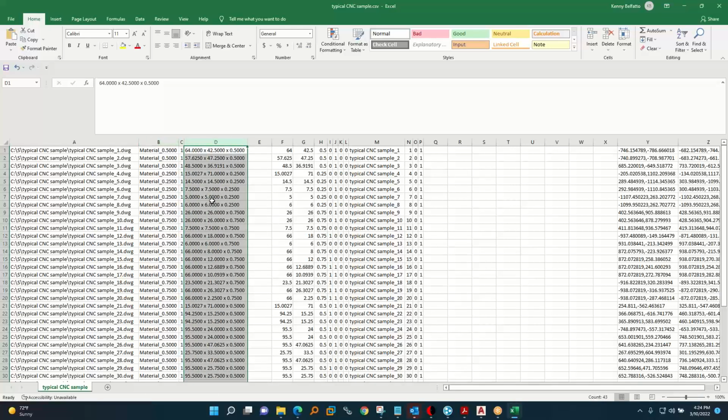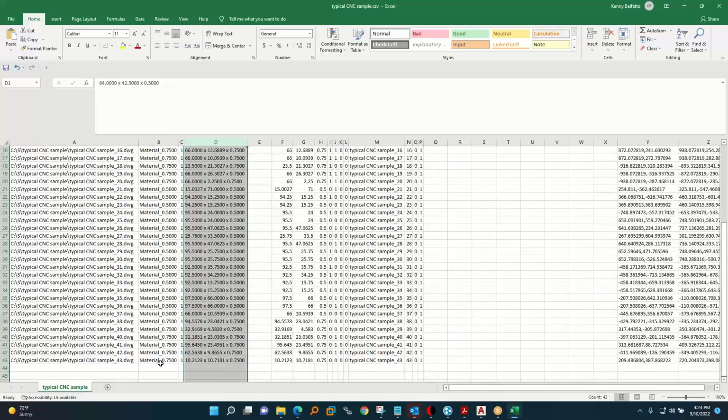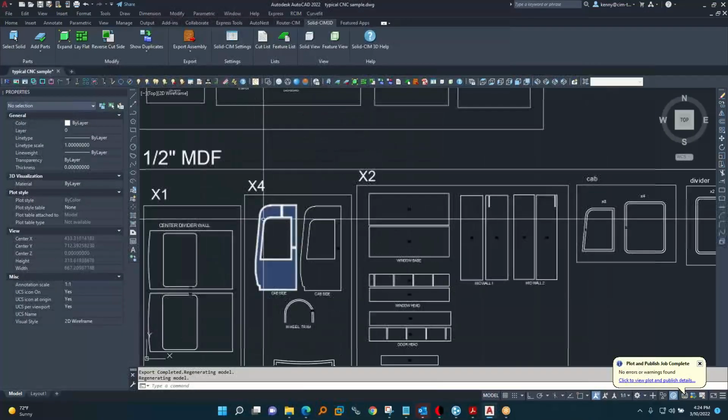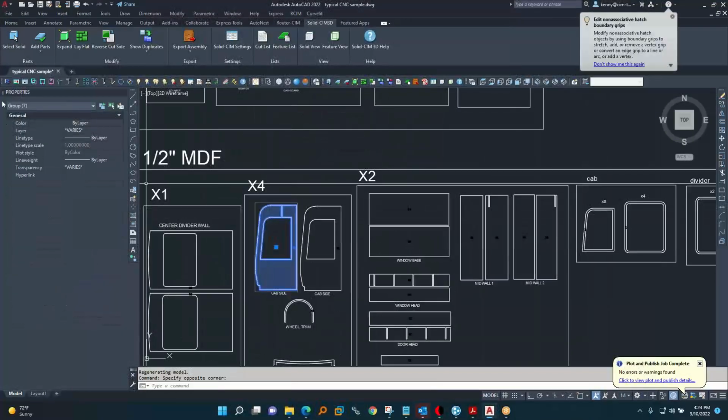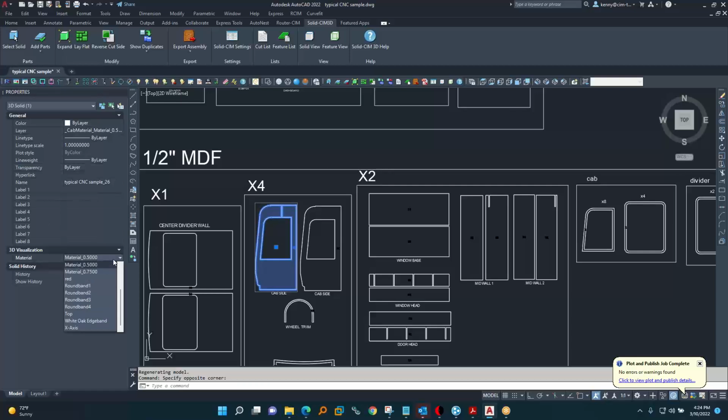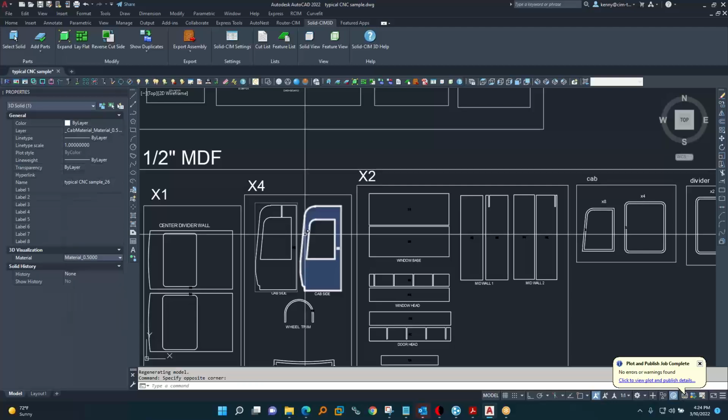So each one of these, if you didn't use a material, it separates them by material thickness. And if you do use materials, it uses the material information. You also could put in label fields on a 3D solid too. So when you pick a 3D solid, look, you get to put in the name of the solid and 8 label fields right there. And then you could use any of the AutoCAD materials. So oak and things like this, they're all just materials using the RMAT command.